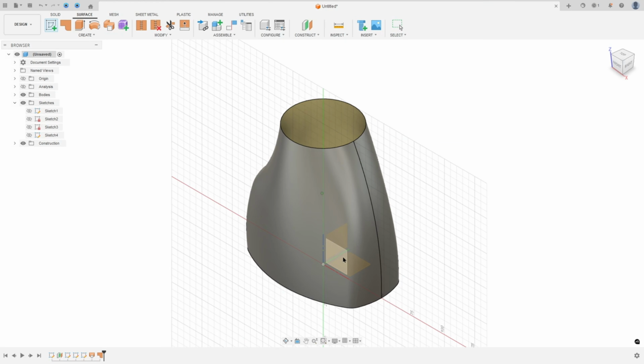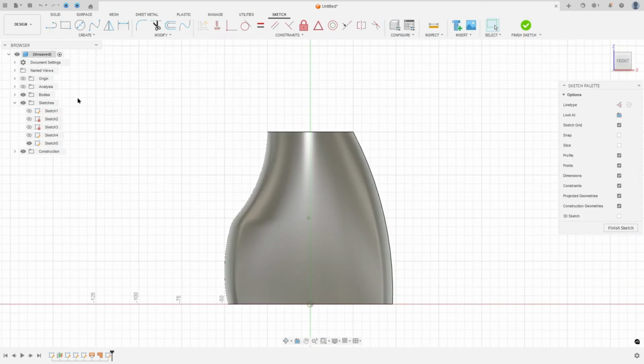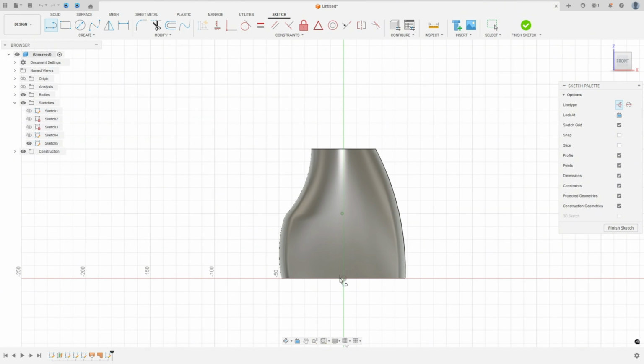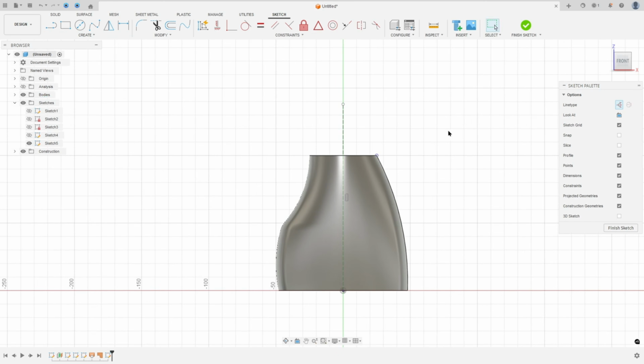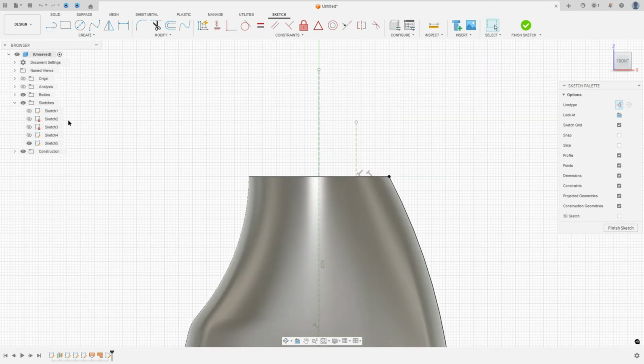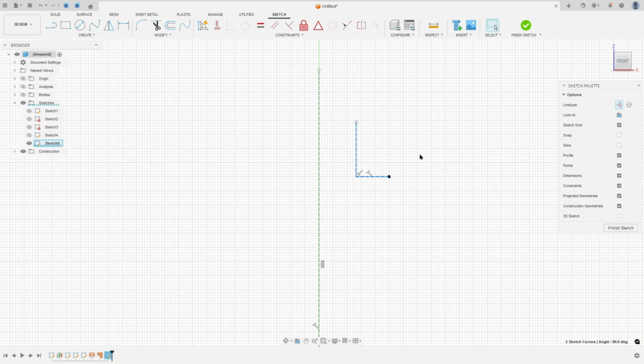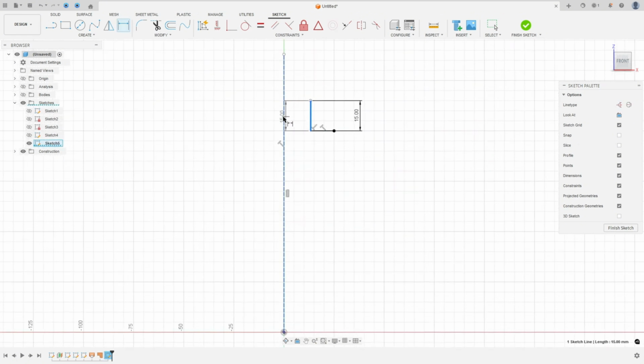So go to create a sketch, select the front plane, select line, a construction line, click at the midpoint, make a construction line here. And go to create and select project include, intersect, select this point here, press OK. Now select line, make a line here and another line here. Remove the construction line type, sorry. And go to sketch dimension, the distance here 15 millimeters, and the distance between these two lines 17 millimeters, okay?